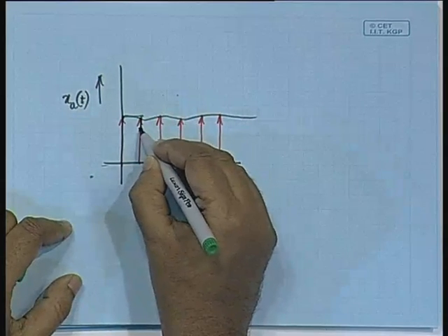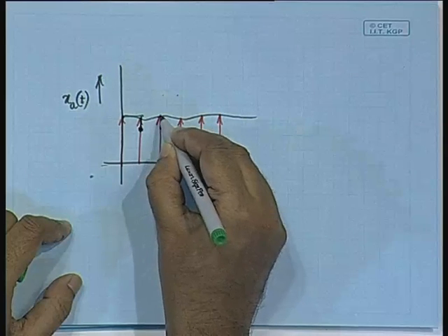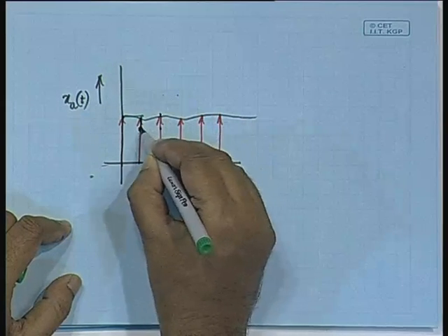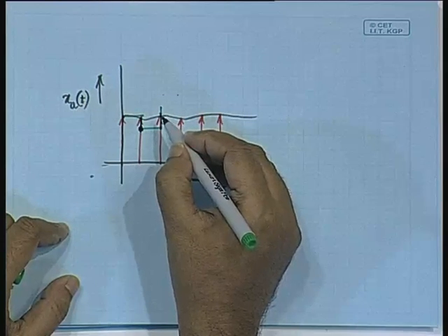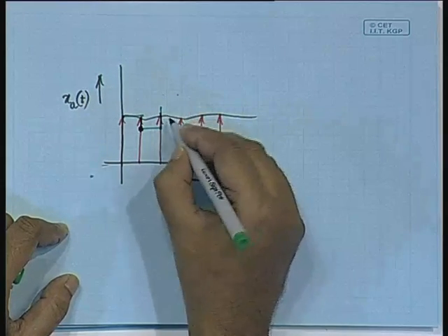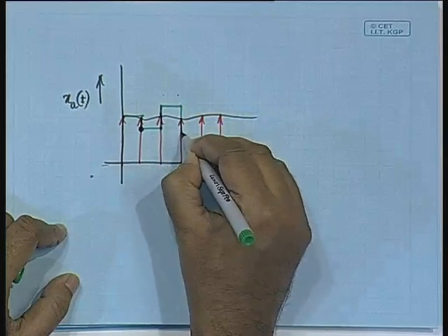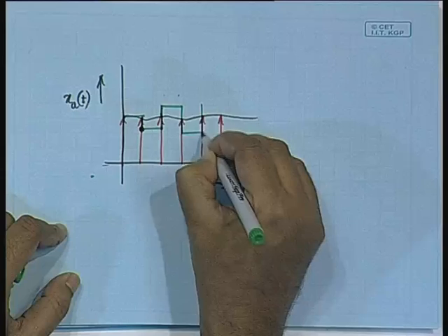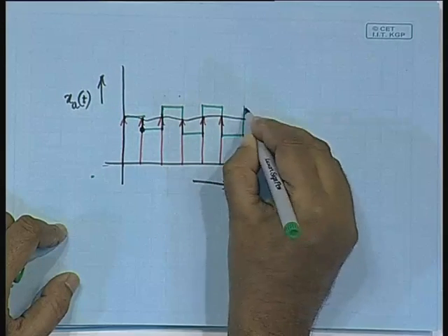Now, the predicted sample is going to be lower than the next sample. So, we increase it by delta, and mind you, we have decided to have a higher value of delta. So, with a higher value of delta, it goes up, next time it goes down by the higher delta, next time it goes up by delta, next time it goes down by delta, like this.